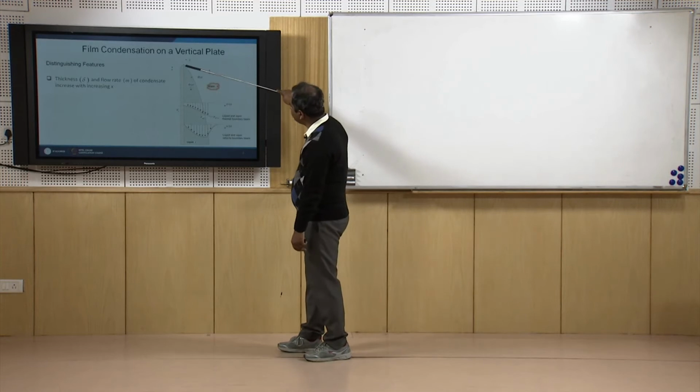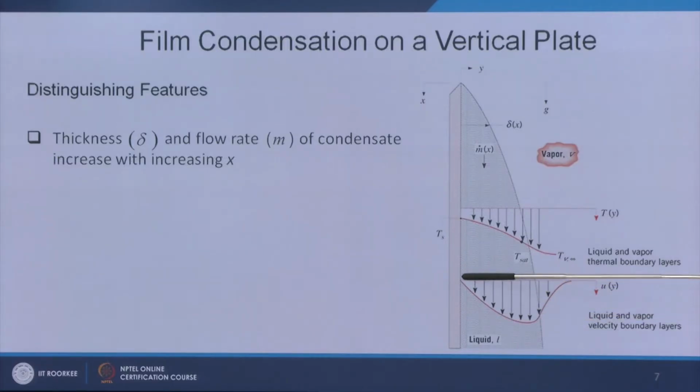So, you will find out there is a flow also occurring in this. So, the velocity profile can be shown like that. Due to no slip, it will be having 0 velocity adjacent to the wall, and far away from the wall where there is no film, obviously the velocity will become 0. Okay. At the interface, so you can see a parabolic profile like this will be generated because film is draining from the top, it will be accumulated at the bottomward side. So, you will be finding out thicker film at the bottom and thin film at the top. So, near the film you will be finding out there is continuity between the liquid velocity and the gas velocity.